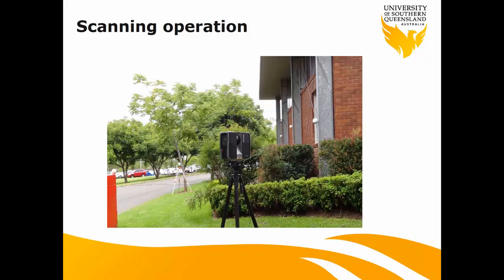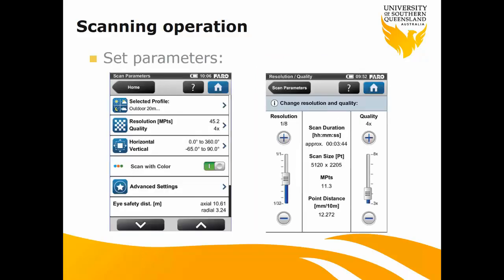That also depends on the different settings, for example, how dense the scanning points are and how big the scanning target is. That will affect the distance between the target and the instrument.